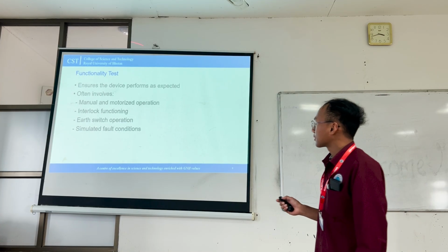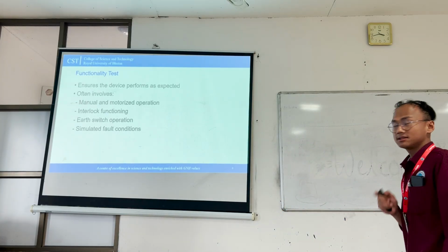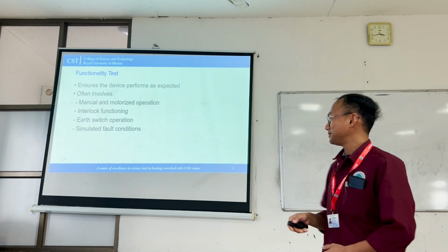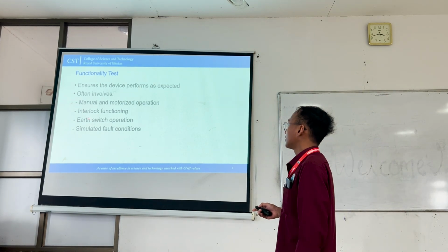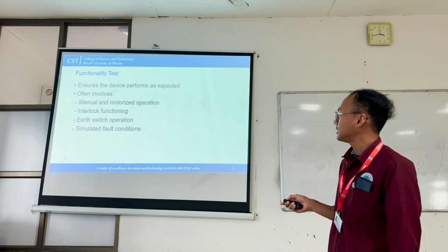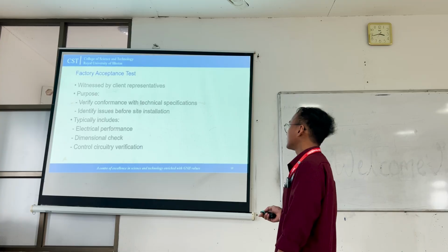Now, coming to functionality test, this test ensures that the device performs as expected. This test includes manual and motorized operation, interlock functioning, arc switch operation, simulated fault conditions.